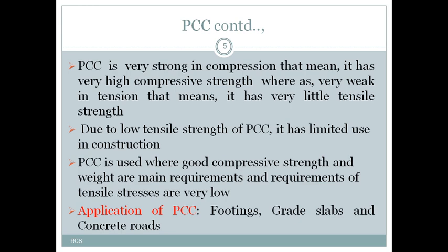Further, we can use PCC at many places where good compressive strength and weight are the main requirements and the requirement of tensile stress is very low. Applications of PCC: we can use it under a footing as an impermeable layer.